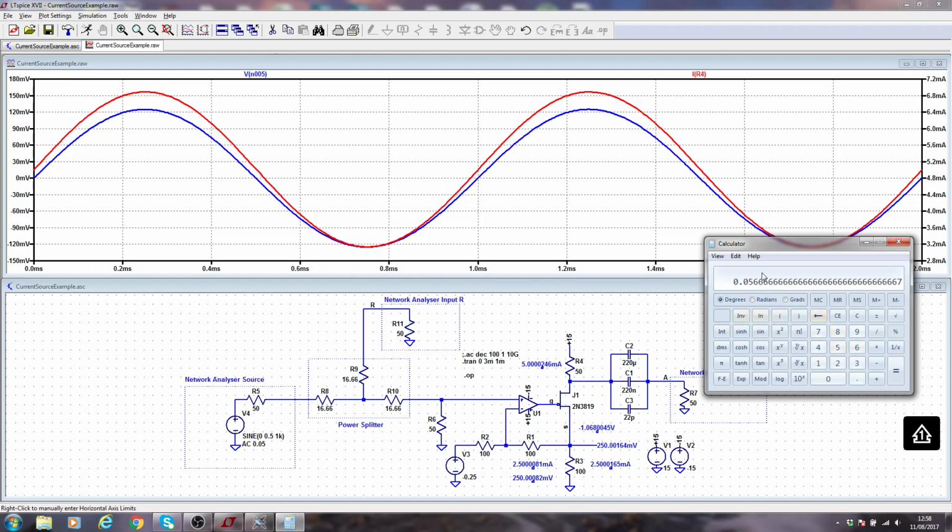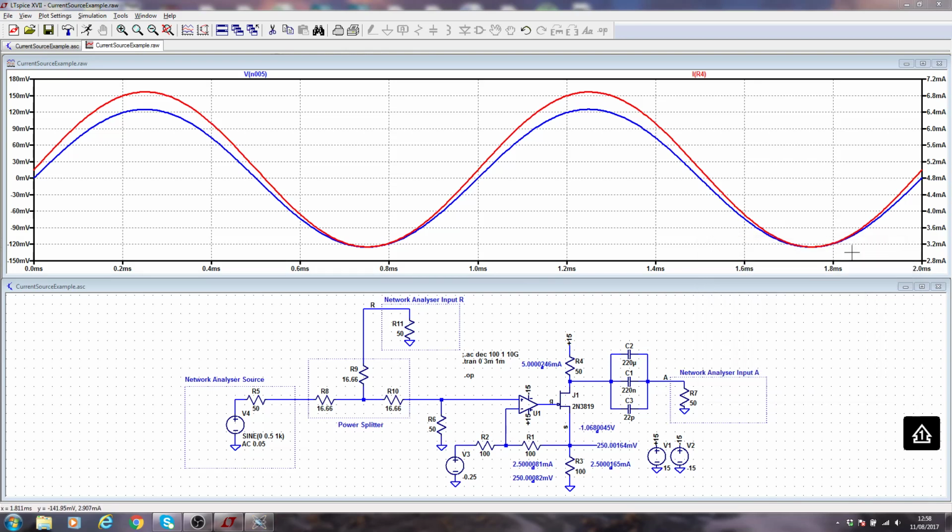It's usual to do this in milliamps per volt, but I did it in the base units just then. As far as current is concerned, it's in phase. The reason for that is as this increases, the current here, in R4, it makes the voltage drop across R4 bigger. Consequently, if we did 15 minus the increasing voltage drop across R4, the voltage from here to the ground is actually dropping, because this voltage across here plus this voltage here must add up to the plus 15. This one is getting bigger, this one must be getting smaller. That's why we end up with the phase reversal. This current gets bigger, this voltage gets smaller.